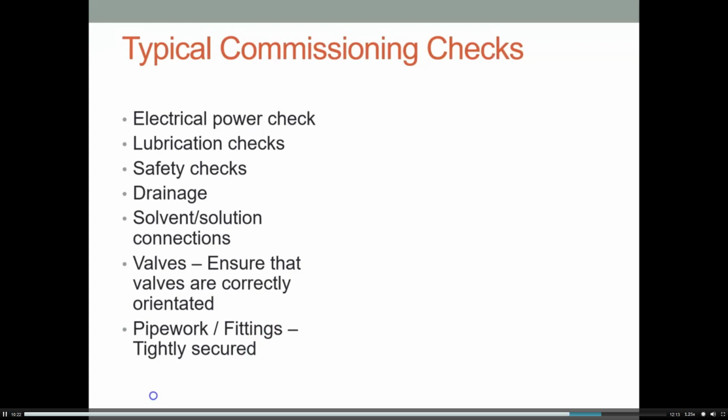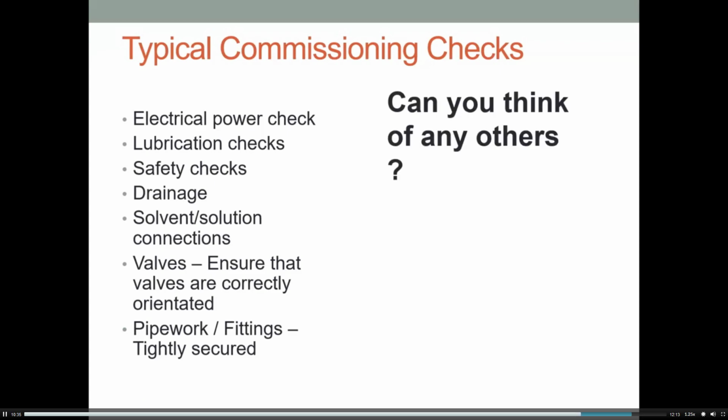Solvent or solution connections: will you need to be hooked up to solvent lines or purified water lines or water for injection or whatever? Valves: making sure that your valves are all correctly oriented and working properly, and your pipework and your fittings are all tightly secured. Can you think of any others? Just take a minute and see if there are any other commissioning checks that you can think of.